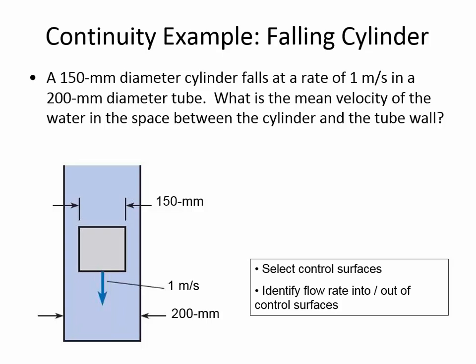The trend continues, comparing theoretical and experimental. Most of these labs through the semester, we're trying to see how good are the equations that I'm giving you. These equations like Bernoulli's equation, Reynolds number equation, momentum equation, which we'll get into next week. How good is the momentum equation? Does it work in the real world? If not, how big is the difference? What's the percent error between the experimentally determined force that's generated and the theoretically predicted force that's generated?